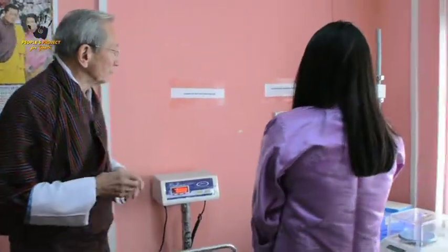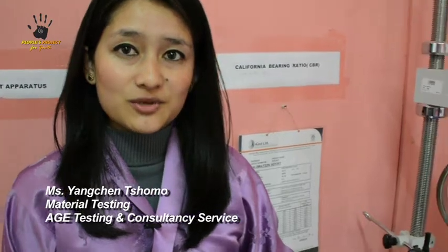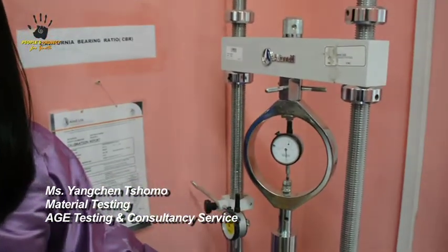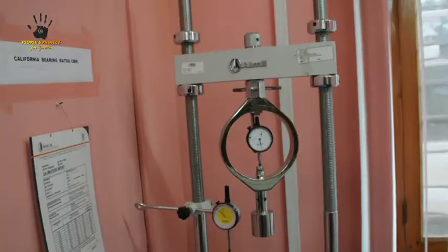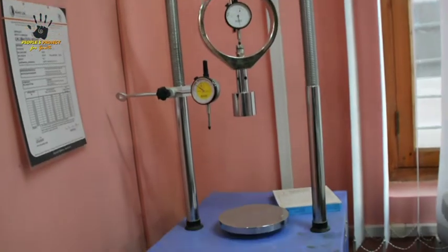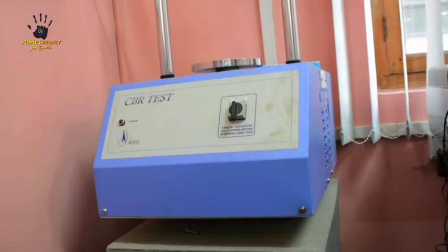Now, what does this do? This apparatus here is California Bearing Ratio, which is also called CBR apparatus. This is again to study the foundation or the strength of the base before you construct the road, and that helps you to design the thickness of the pavement.